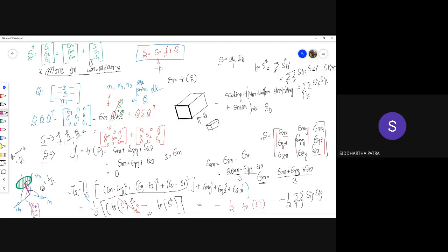In the principal coordinates, and then to give the deviatoric part, which is actually perpendicular to the hydrostatic direction. That's what we have been talking about, right? That the product of these two must go to 0. So if I take the dot product, this would be sigma m times S1 plus S2 plus S3. Again, S1 plus S2 plus S3 is the trace of the deviatoric stress tensor in the principal coordinates, but the trace, or J1, being an invariant, is 0 all the time. So this dot product is 0, which means these two vectors are orthogonal to one another. And this right there becomes our S star, represented as a vector in principal coordinates.